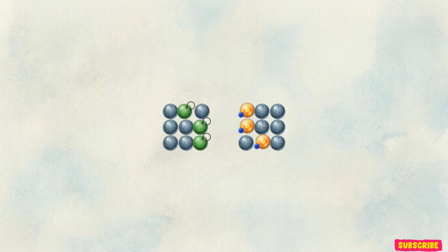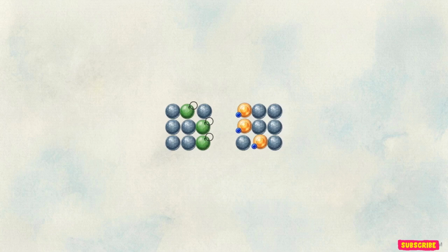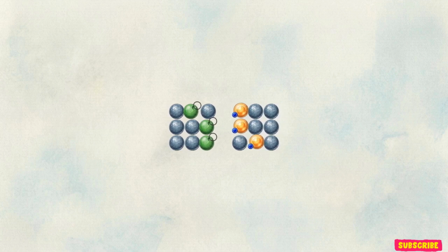The critical mechanics of the diode are initiated the exact moment these two differently doped materials are merged to form a single junction. Because there is a high concentration of free electrons on the N side and a high concentration of empty holes on the P side, a process called diffusion begins immediately. Free electrons naturally migrate across the concentration gradient at the border to fill the empty holes on the other side.